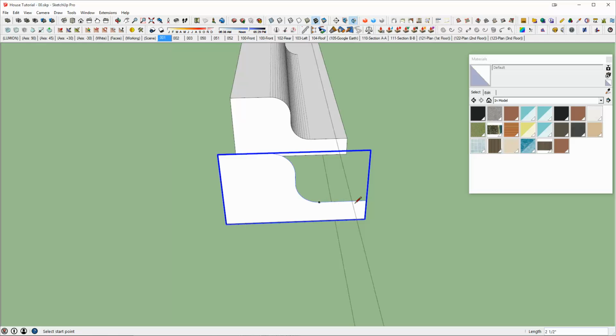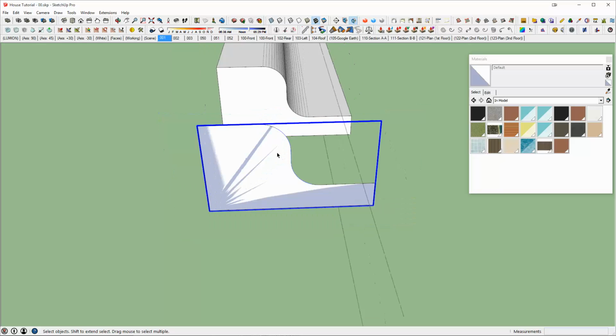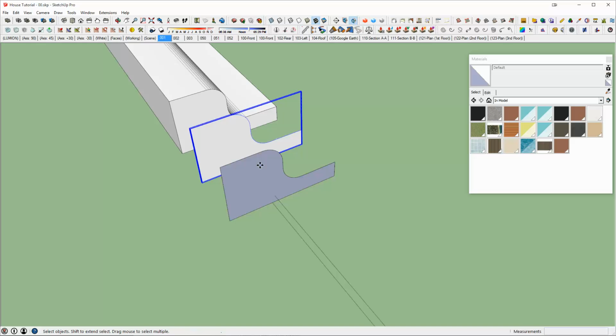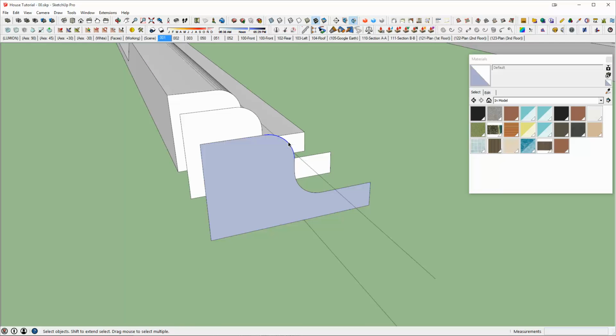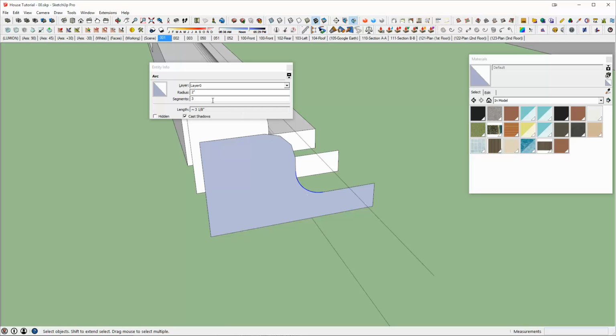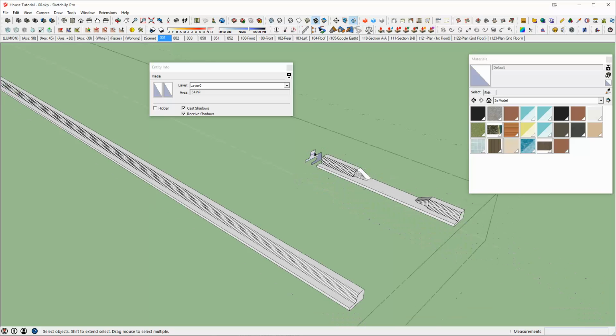I'm just drawing all the straight pieces real quick, and now we can come in and draw my arc, and this arc, to there we go. And we'll move the old one out of the way right over here. Now you can see that if I come in here and hit Shift E, this is 12 segments, which for a curb and nothing we're really going to focus on, that's way too much for what we need. We'll maybe be able to go to 3 and really reduce this and make it much easier to deal with.